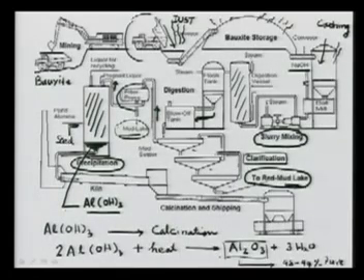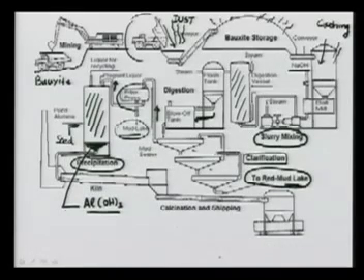But we haven't looked at how this calcination is really done. Here we have the aluminium hydroxide that is passed through the kiln. Kilns are rotating tunnels. Let's make it rotating to indicate with the arrow. The kiln is rotating, and then we are supplying the heat through a furnace, and most of the time we use a fuel for the heating.